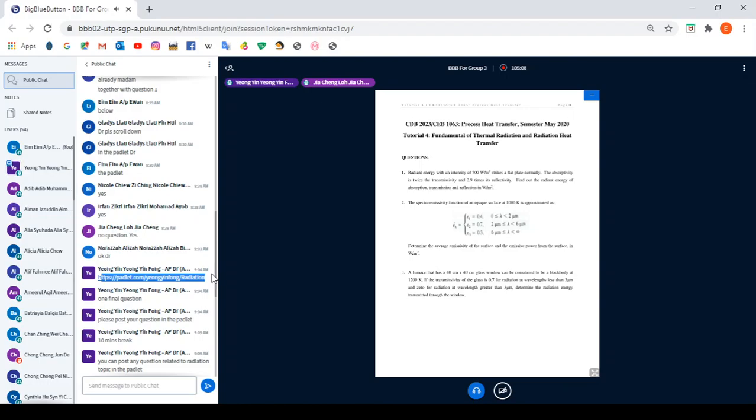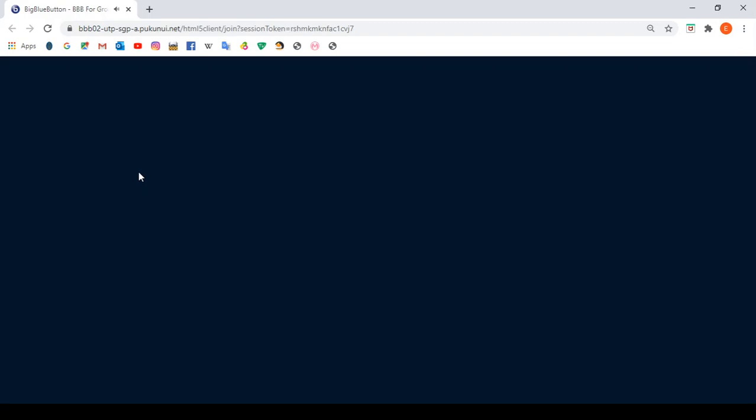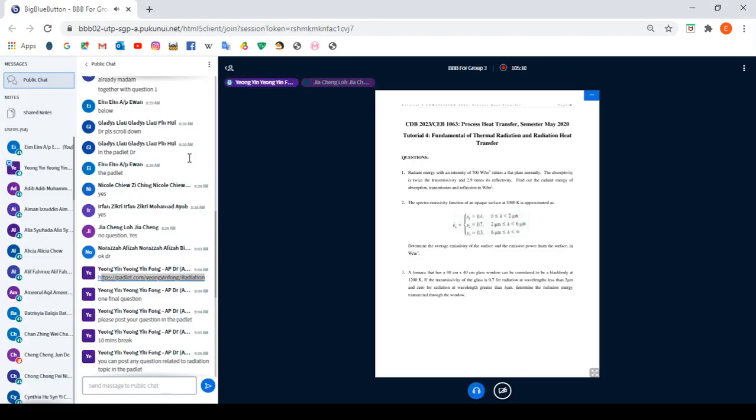And then for LT in laminar flow, that one is for Ts constant. After I calculate, for example, I get 0.1. That means beyond that 0.1 it is fully developed. Yes, it's no longer developing. You need to use the constant Nusselt correlation value. So I have to use Nu equals 3.66, if it is Ts constant. Yes. All right, thank you.